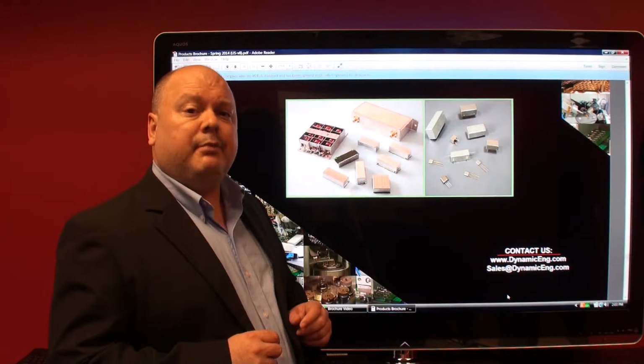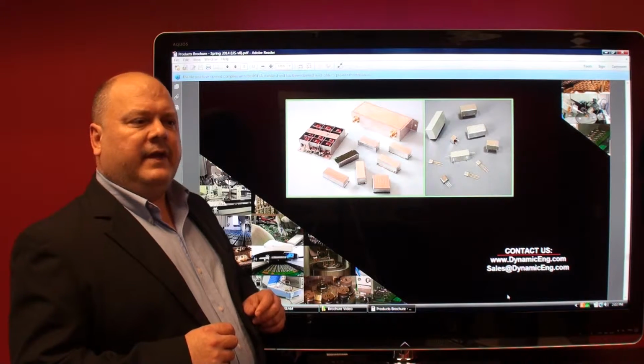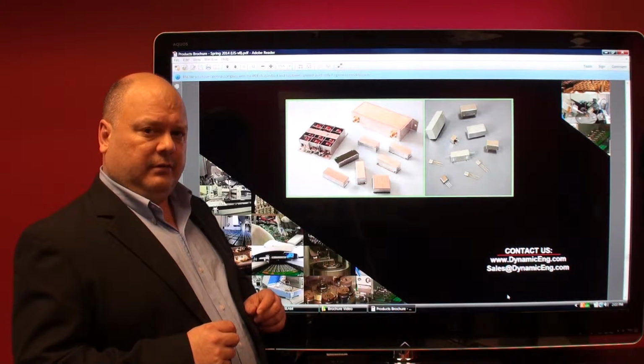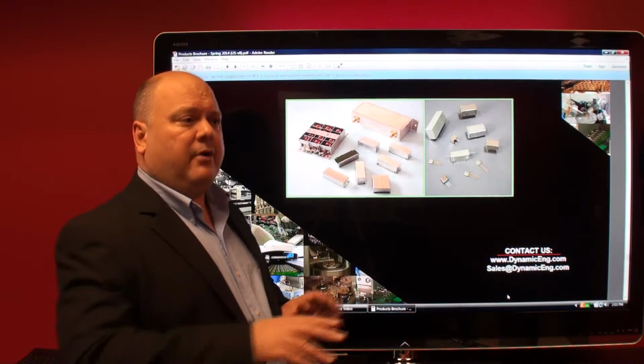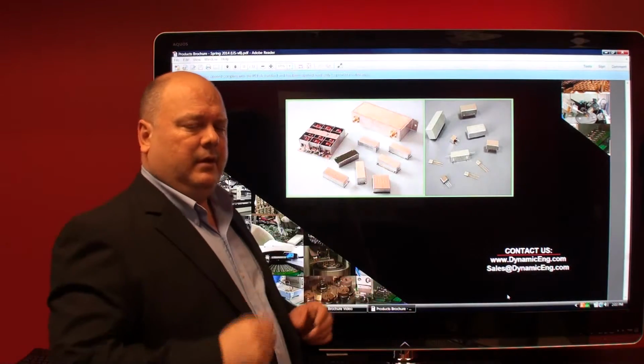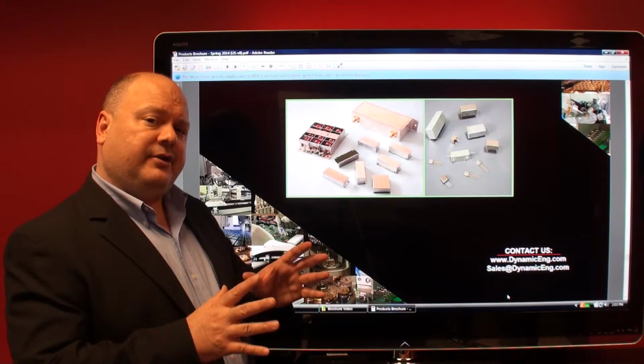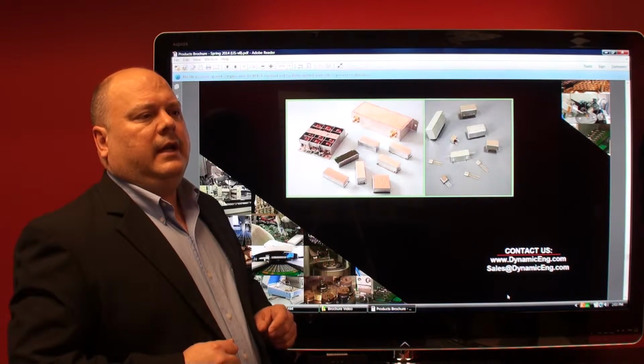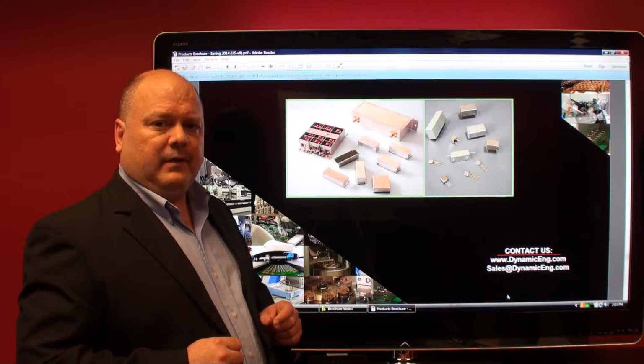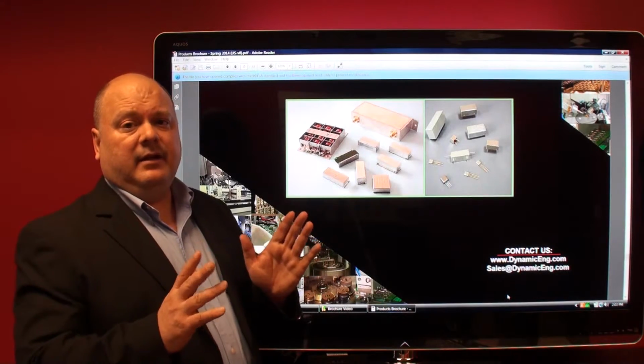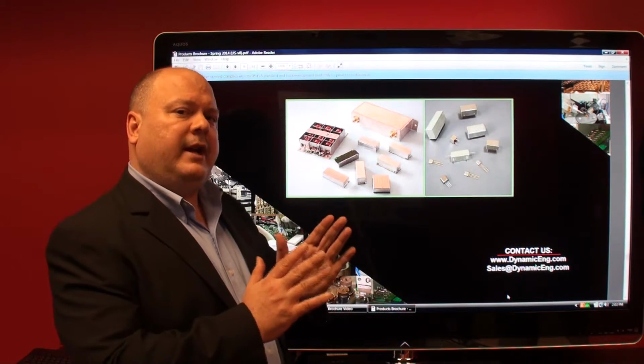that is in the brochure. And the IF crystal filter, the intermediate frequency part of the radio, the wireless system, is where you'll find crystal filters. In the IF system, that is basically your passband is the channel spacing in the radio.